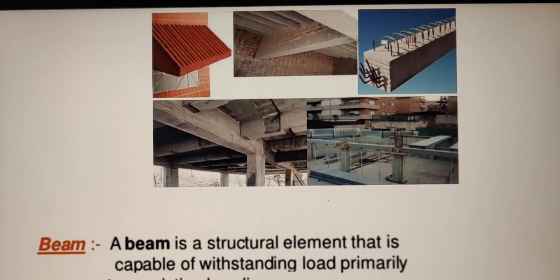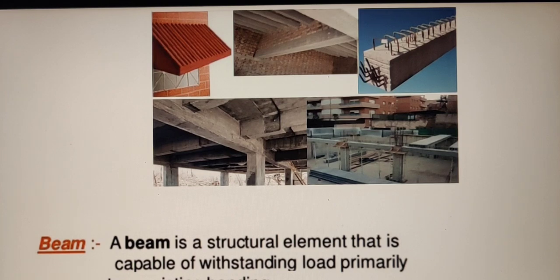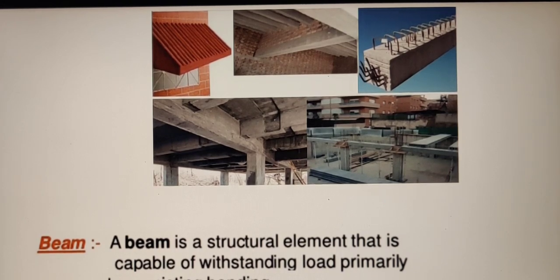Due to the application of the load, reactions are developed at the support, and the system of force consists of applied load, self-weight and the reaction. All these forces, external force along with the reaction, keep the system in equilibrium. The force constitutes a system of coplanar non-concurrent forces.